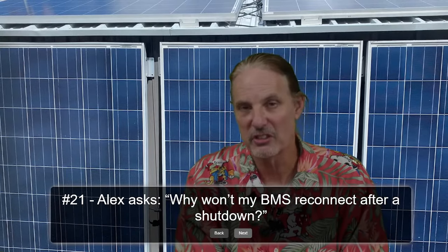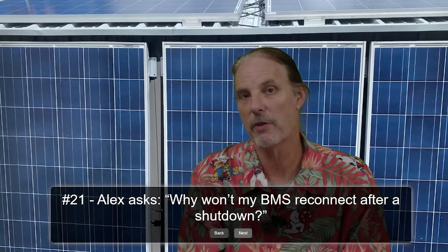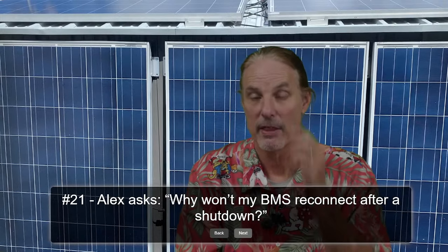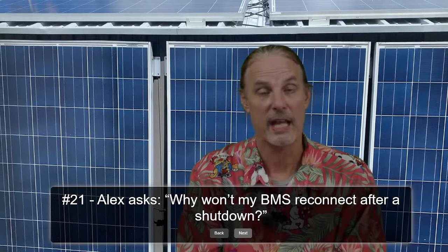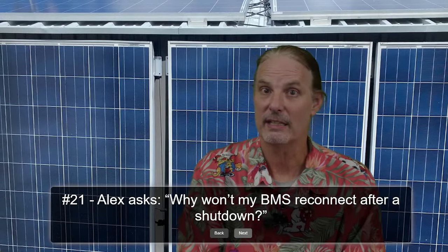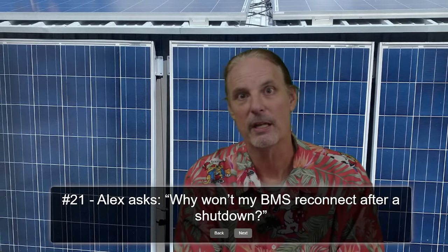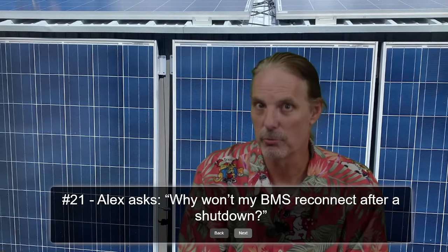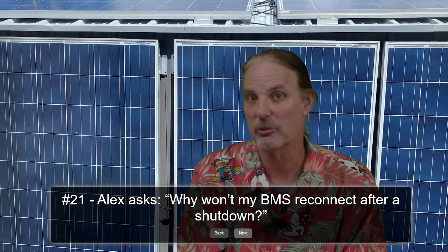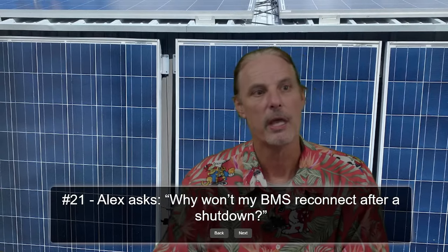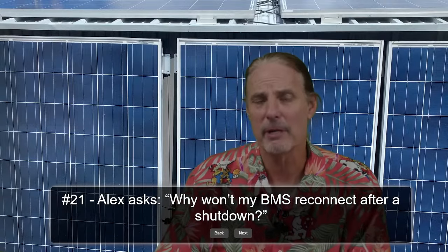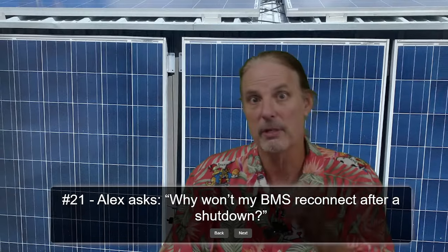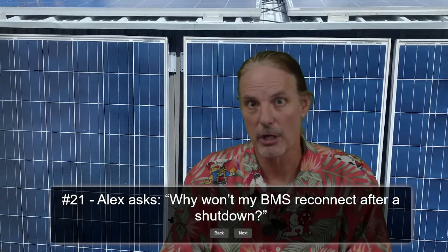Most BMSs these days, and you'll see from the video that I produce that comes out the next day or two from the Lead Time battery, the 24 volt one, had exactly the same thing. When it shut down, it needed a trickle charge, and I confirmed that with a bench charger that would work. But I also confirmed that the Victron would reset it also, and I also know the 6000 XP would enable it. So several different ones there, but your battery may just not be configured to come back on correctly, or it may require human intervention depending on what kind of charger and everything that you have.